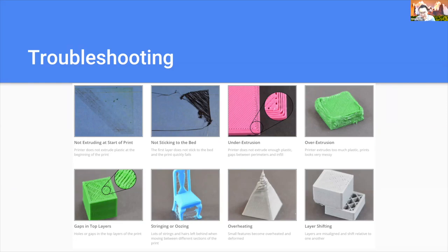And then there's too much heat for the printed material, right? It doesn't cool down sufficiently. The print head is going to drag the tip of the print around. What you want to do is either increase the cooling or decrease the printing speed for the top layer so that it allows more time to cool.